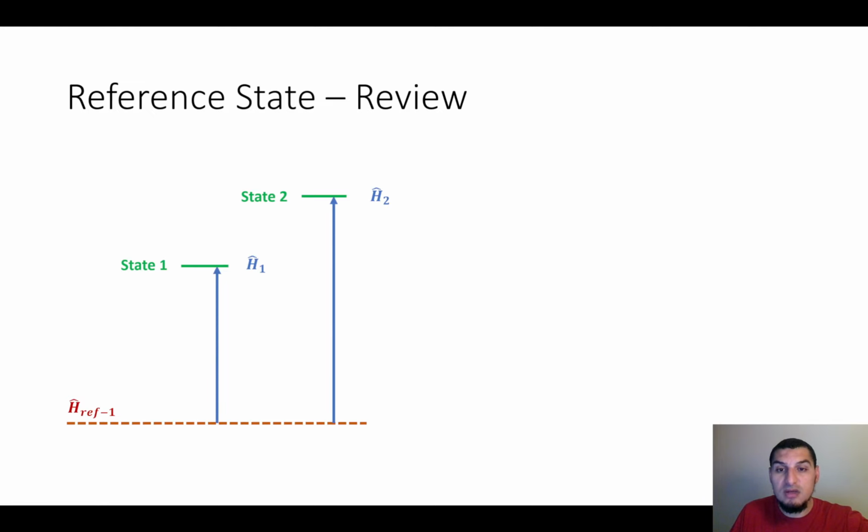So this is what we calculate as H1, which is not the actual value, it's the value relative to the reference state, and the same for H2. This reference state is the state of the matter at a specific temperature, pressure, and phase. And we said that the choice of reference state doesn't matter, the difference will always be the same. If we set another reference state, the two enthalpies will be different, of course, but the difference is the same.